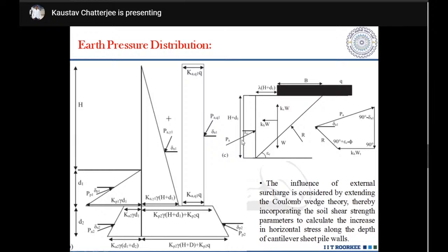And this represents the total diagram, that is, the PA acting, delta P1. Epsilon C represents the angle which the failure envelope makes with the horizontal, and this represents the horizontal earthquake force and the vertical earthquake force over here. That is Kh into W and Kv into W, my horizontal and vertical pseudostatic earthquake forces that we have considered, and this represents my force polygon.